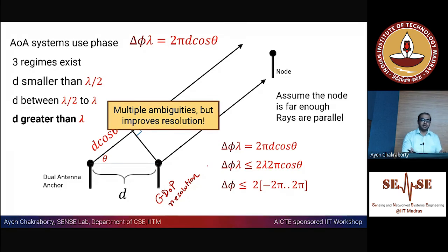Very simple, like common sense, right? If you are having the angle being measured from these 2 points and the 2 points are very close to each other, the geometrical diversity is very less. We also saw that in case of the drone. If the drone's aperture is very small, it is very difficult to find out the precise location of the node given the range errors, right? Here also in the phase calculation you will have some error, so that is going to give you poorer resolution if the distance in between the two antennas is very small. However, it is going to have no ambiguities.